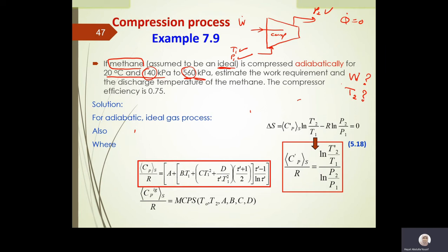It is not steam, where I can use T1 and P1, go to the steam table and get the properties. So we have to ask ourselves, how can I fully define the system at the outlet? I only have the pressure. In the question, the compressor has an efficiency of 0.75. For a compressor, efficiency is delta H dash over delta H, or delta HS over delta H. So for the isentropic condition, I will get delta H dash, and then use it to get the actual property, because the actual property is the denominator here, which is W, which they need in the question.